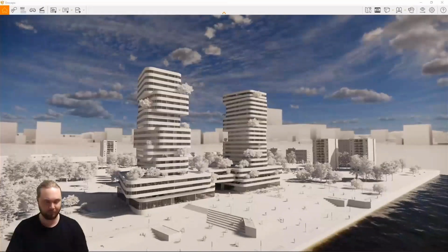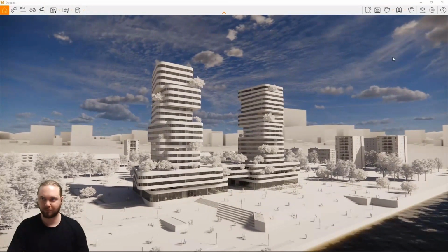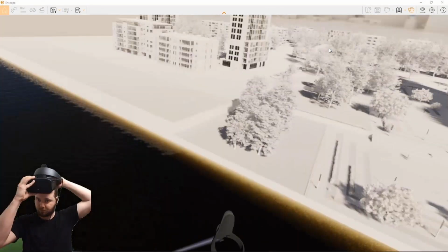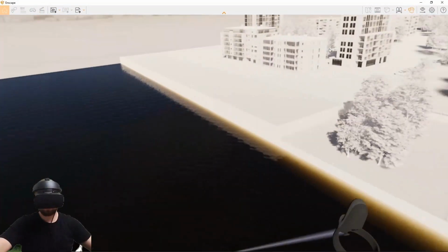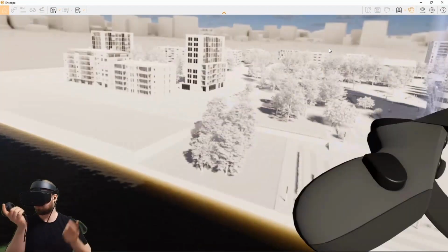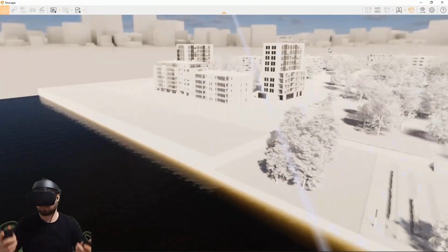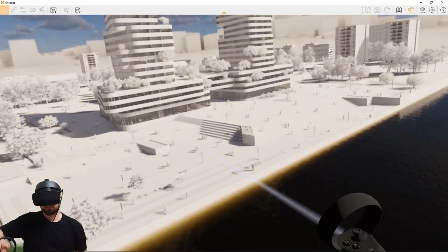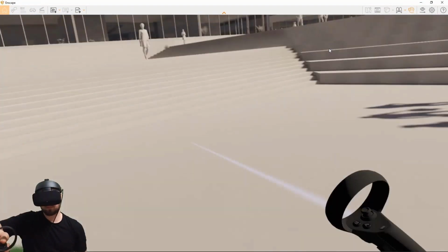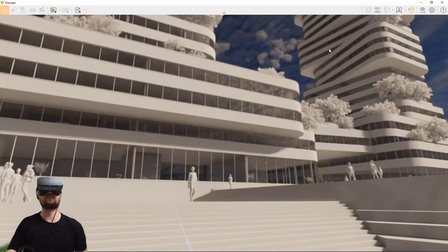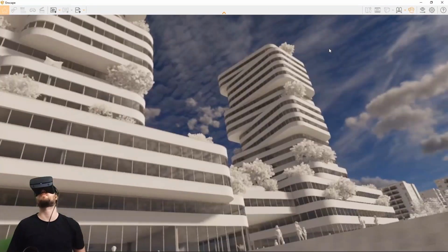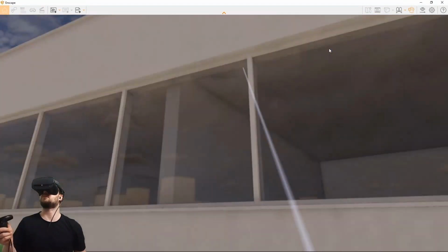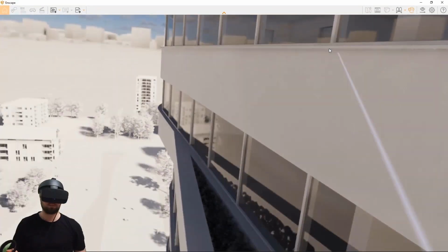So yeah, great. Here you see a recording of me this morning where I just simulated a usual use case. VR with Enscape is terribly simple and easy to access. I literally just click the button in the upper right corner to enable VR, and I can start exploring the project right away, just putting on my VR goggles. And there are multiple ways you can explore the model. You can teleport yourself, which is great to reduce nausea and movement sickness, and really the depth, the scale of what you see is absolutely realistic.